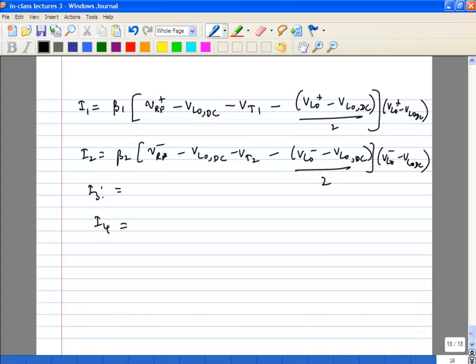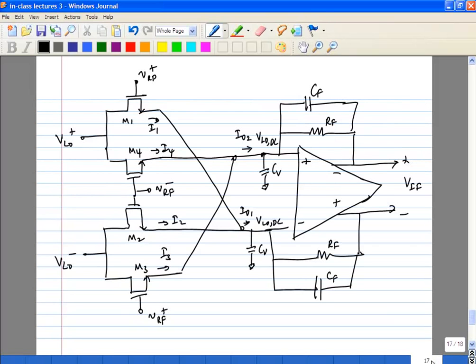And this happens to be a double balanced structure. So what will happen is all your LO feed through terms vanish as long as the transistors are well matched. If there are any nonlinearities due to, let's say, GDS of the transistor, if it's not a perfectly triode behavior, that will get cancelled to a first order.